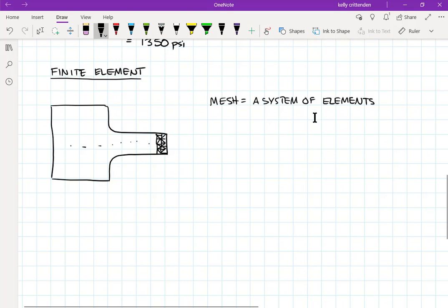Somewhere you have to have some boundary conditions. Usually in our case, we're going to say that this edge, or this face, because it's three-dimensional, will be our boundary condition, and that this is fixed. Or maybe you create a boundary condition where something is hinged so it can rotate, or whatever. There are lots of different boundary conditions. For us, we'll just glue that edge to the wall. There's no actual wall there, but if it's just floating in space, most finite element solvers can't deal with that.